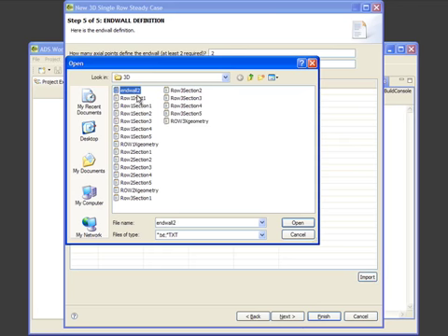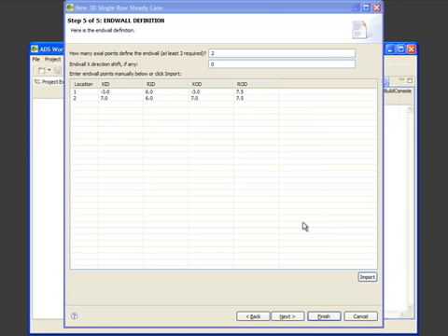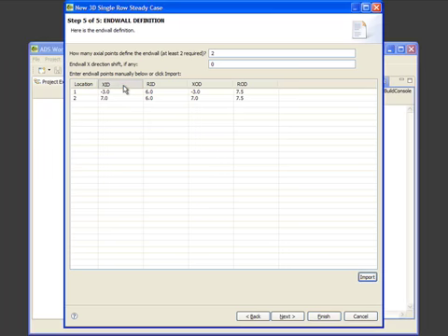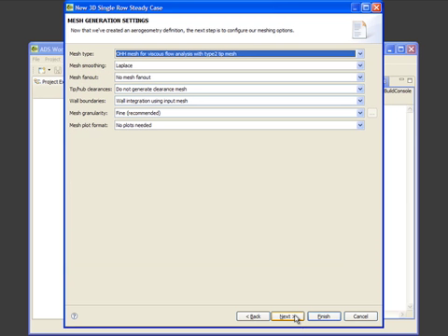Here we have the ability to import an end wall that is already predefined for us. As you can see, our end wall is defined by 2 points, with each point defined by 2 points, one at the inner diameter and one at the outer diameter. It is not necessary that the inner diameter x value and the outer diameter x value be equivalent. So congratulations, we have now completed the aero geometry data entry. We will go into mesh settings.